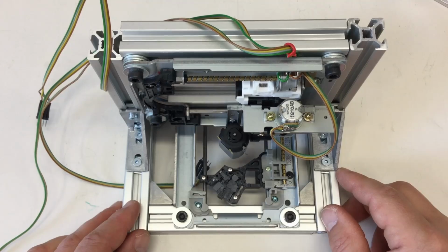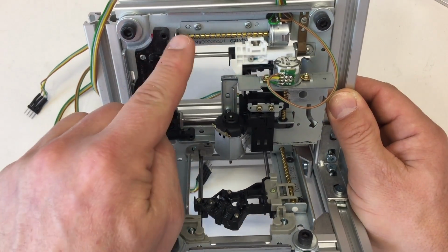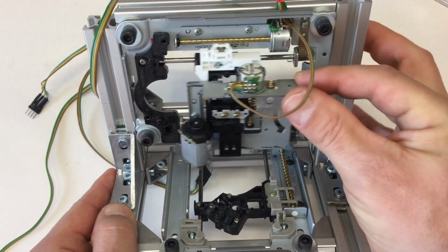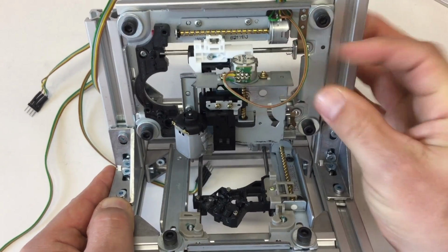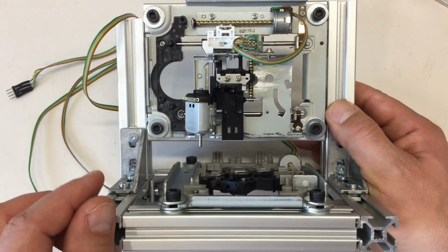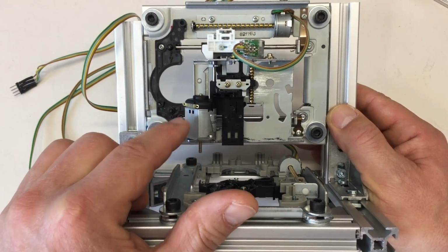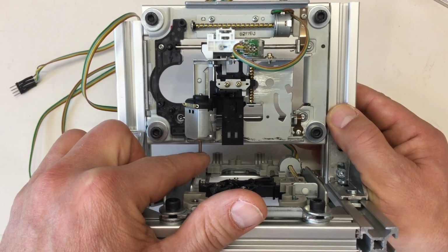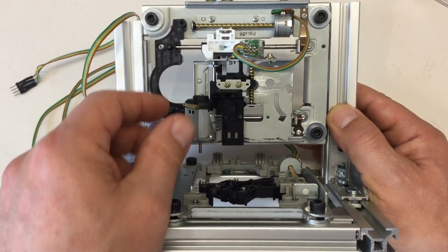Today I want to calculate, as a first step, the load on my X bearings, the upper and the lower one. Yeah, that's my X-axis on the gantry. When I put Z force on my cutting tool, that is basically drilling down into my material, and that results in a force pushing up on my spindle axis.